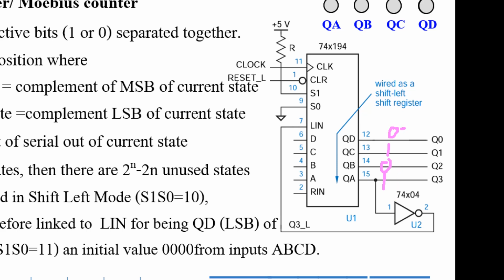When the clock ticks, copy these 3 bits 0, 1, 0, and this one is inverted, then it becomes 0 here, then becomes 0 here, for example. And then when the clock ticks, 0, 0, 1, 0, 0, 1, this is 0, then inverted, it becomes 1, 1 here. Okay, and so on. Write down all possible states. Okay, you can see that this circuit cannot get back to a normal state.